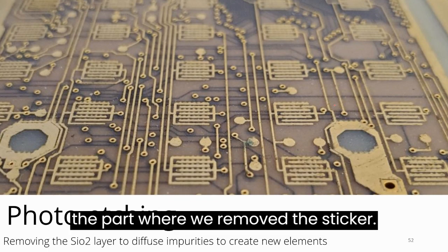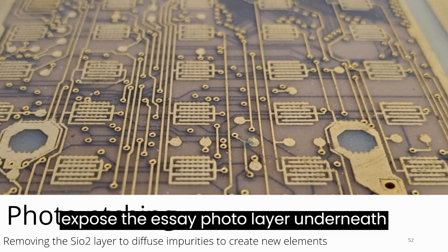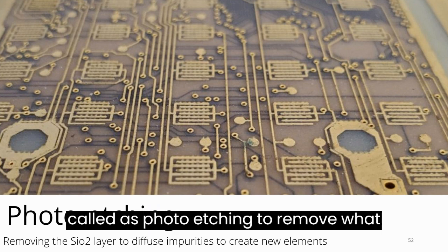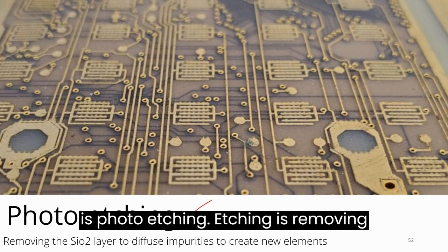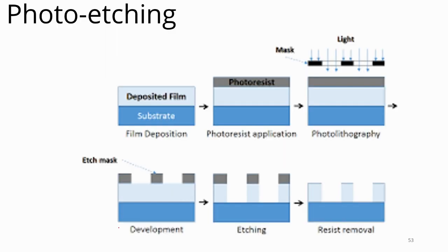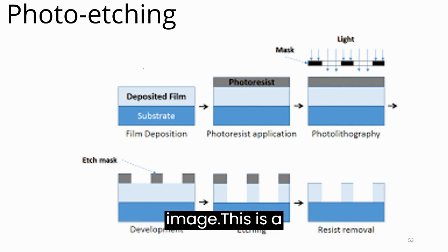After that, the part where we remove the sticker will be exposed, right? We'll expose the SiO2 layer underneath it. So what we do is a process called photo etching to remove it. What is photo etching? Etching is removing, and using light to remove is photo etching, right? You can understand it much better with this image.